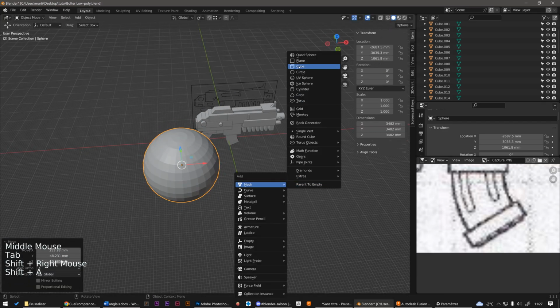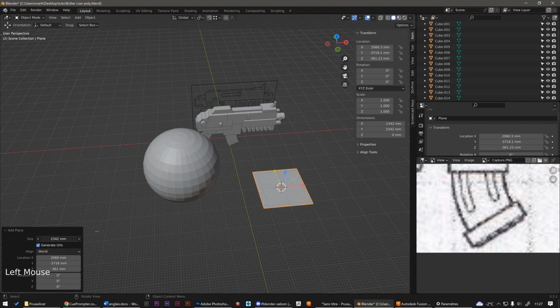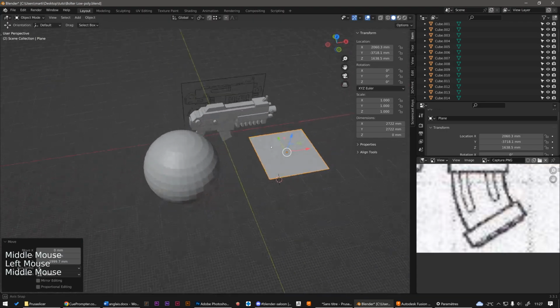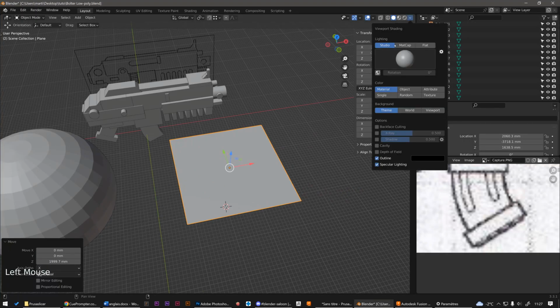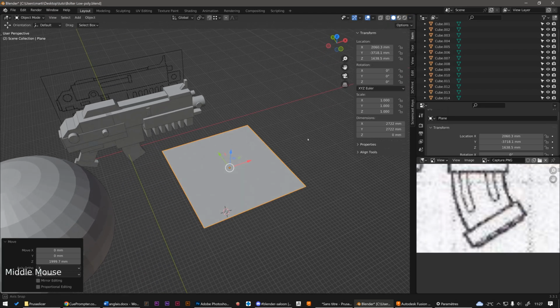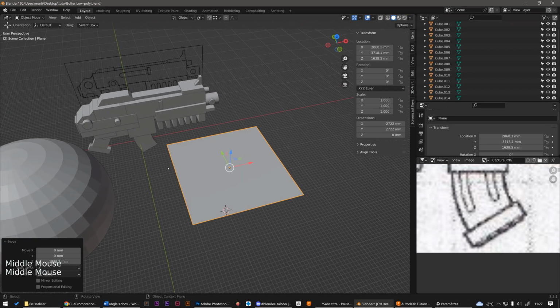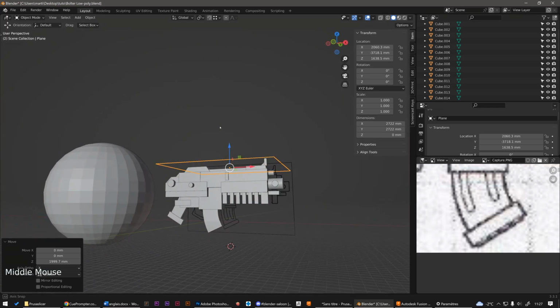So to illustrate this, I'm going to create a plane, which is actually a single four-sided face, and in the 3D viewport display settings, we can enable an option called backface culling. And now, we can see that one side of the face is clearly visible, and the other side is perfectly invisible.